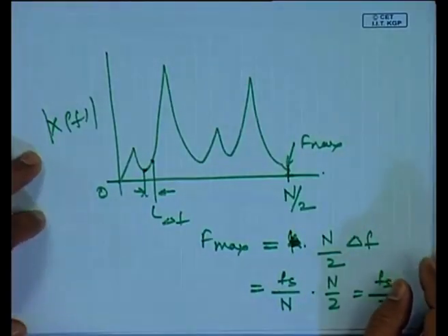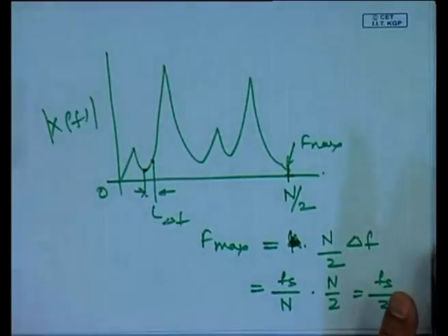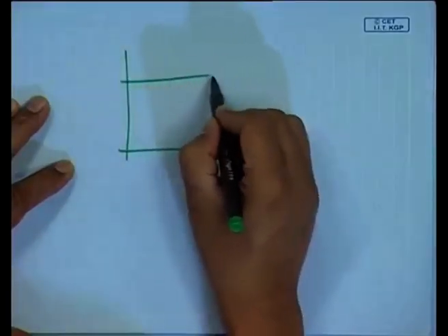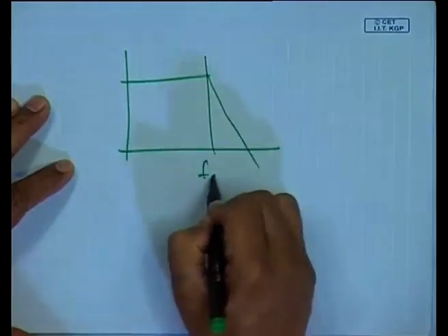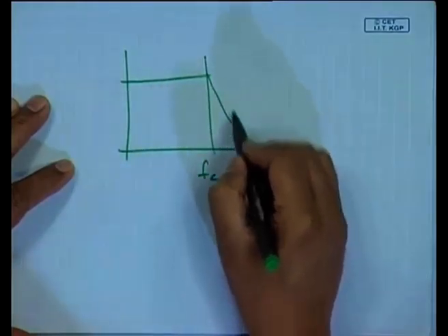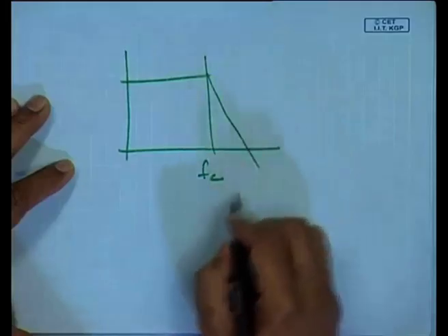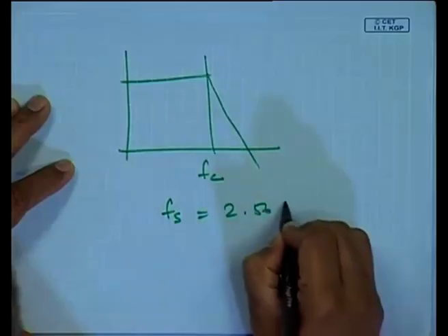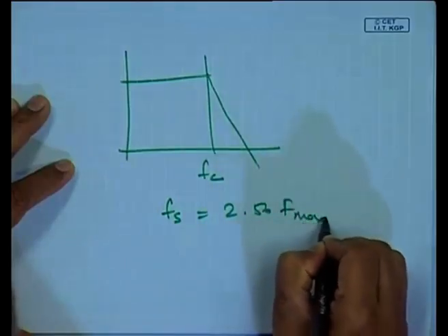So, when I am talking about analyzing an audio signal out of a CD player coming out at 20 kilohertz, I should sample at 40 kilohertz and above. And usually, because of these filters, they have a roll off, when I say a low pass frequency at FC, but because of this roll off, some data comes through. So, usually we sample at a value of 2.56 times f max.